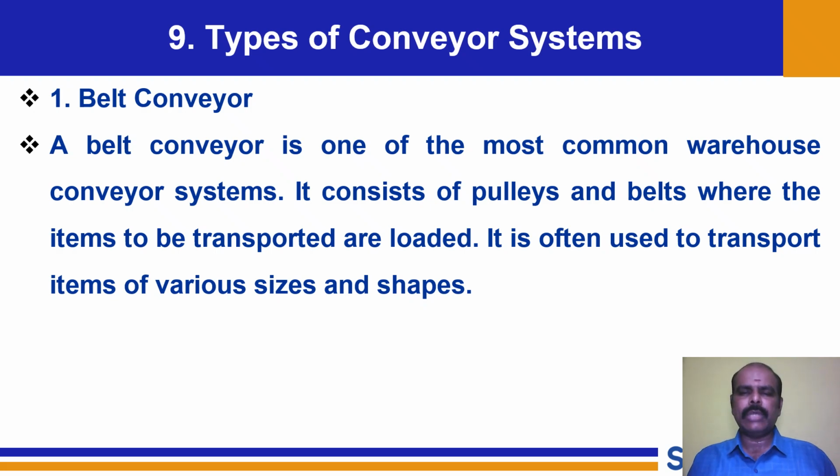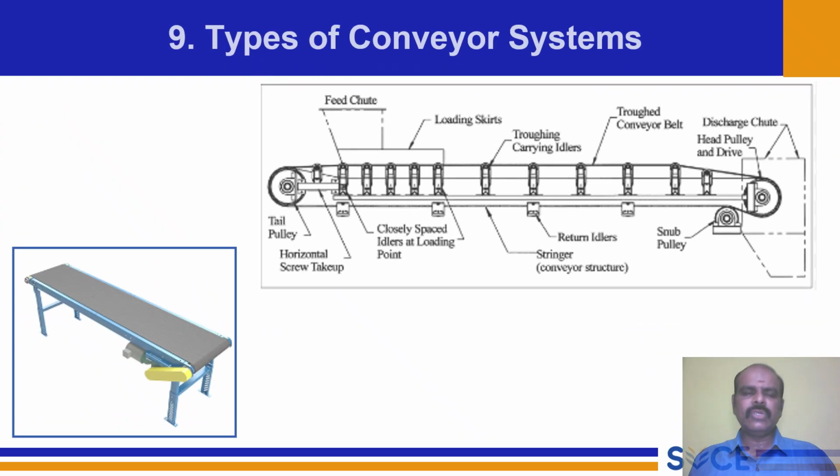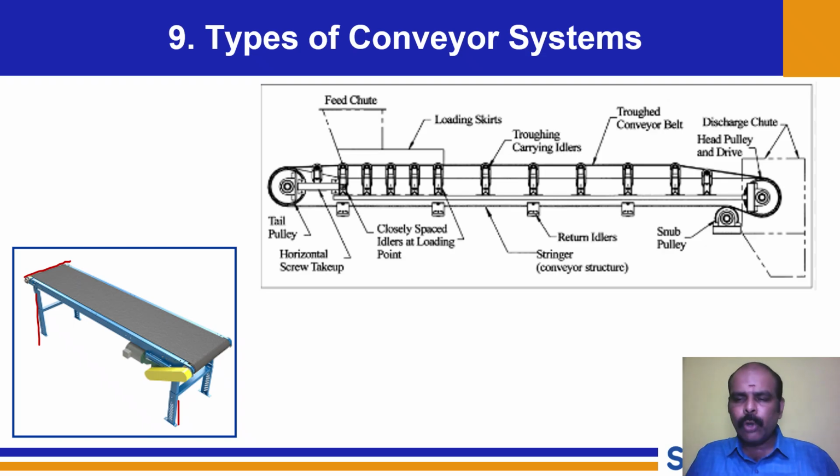We'll see the design, the cross-sectional design. This particular part, what you see, is very simple, right? It's a simple table, a platform, an elevated platform. We have a motor, and one end is going to be the driver and the other end is going to be driven, and in between you have a belt, a completely closed belt, which has some amount of tension. Why? Because if you don't have sufficient tension, there will be slack.